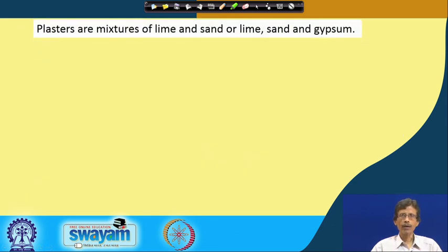Once you get that type of concrete, you have to have the corresponding plaster, because we cannot expose the concrete to moisture and the environment, as the environment will degrade it and it will not be very stable. So we use a coating agent, coating with plaster. You make the plaster, then you coat further with plaster of Paris or lime, the lime cream pasted over there, and finally we go for another coating with paints.